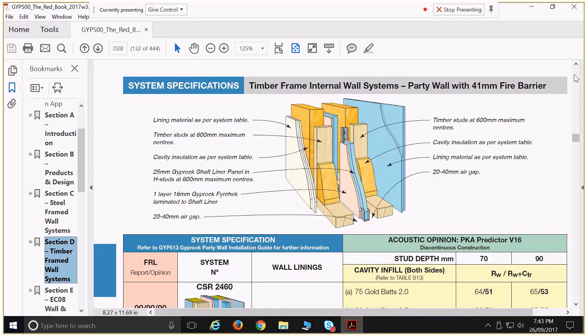What Alex is talking about, and we haven't come across it in the tables, is a scenario whereby we'll have a double stud wall like that, and then a masonry wall built in between. So our masonry wall will provide the fire resistance level, or we would have aerated concrete panel in between the two, fully sealed to provide that fire resistance level as well.